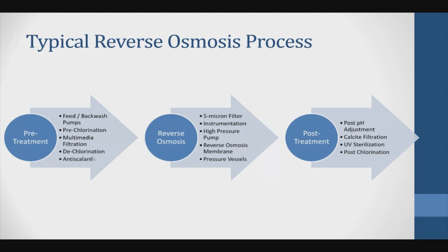The way you notice that the membrane is damaged, you're going to start seeing a lot of leaking of the quality. That means if the membrane is producing 20 or 30 ppm, you're going to start seeing the quality of the water going down, and it's going to start also passing more water. That means if it's giving 100 GPM, you're going to start seeing more water coming out of the membranes.